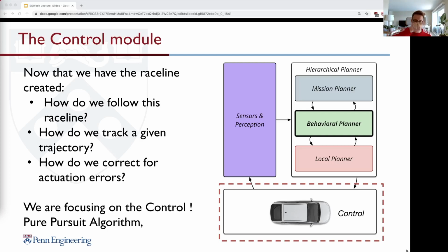And therefore, we are creating our control loop and we constantly repeat that. So our car will constantly do steering and try to follow this race line as fast as possible. In this case here, we show you one particular path tracking algorithm, which is called pure pursuit.